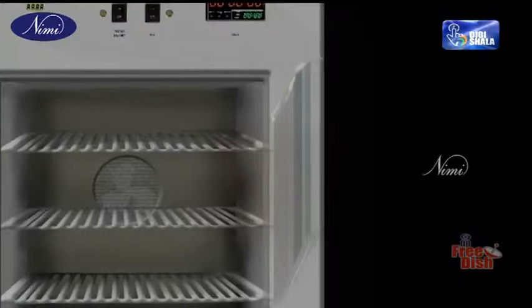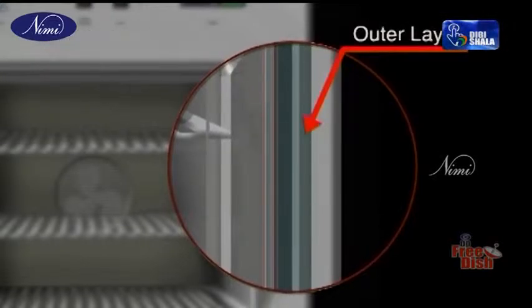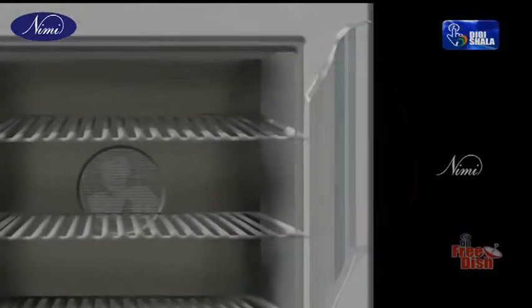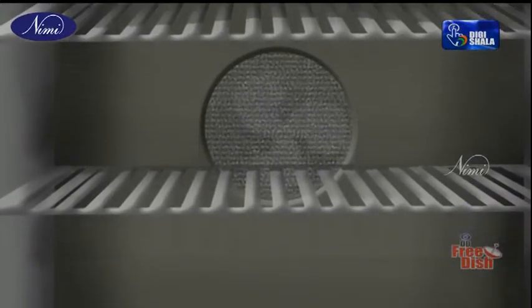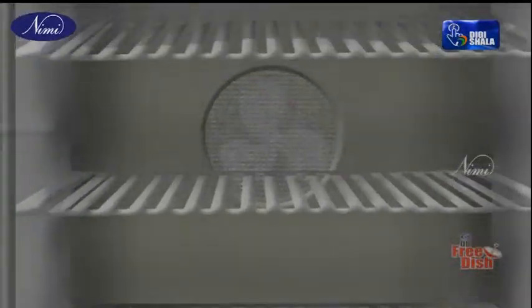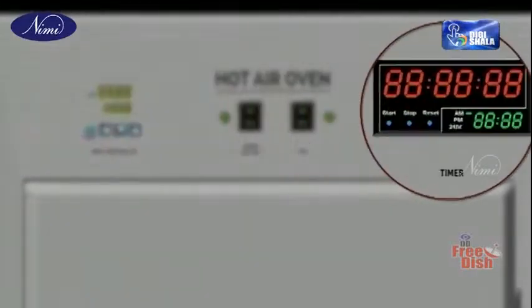Their double-wall insulation keeps the heat in and conserves energy, the inner layer being a poor conductor and outer layer being metallic. There is also an air-filled space in between to aid insulation. An air circulating fan helps in uniform distribution of the heat. These are fitted with the adjustable wire mesh plated trays or aluminum trays, and may have an on and off switch, as well as indicators and controls for temperature and holding time.